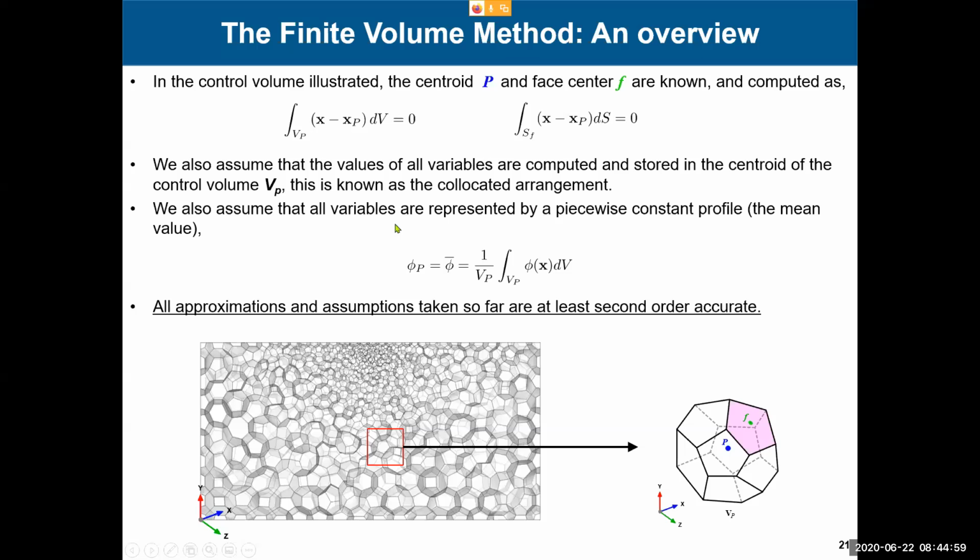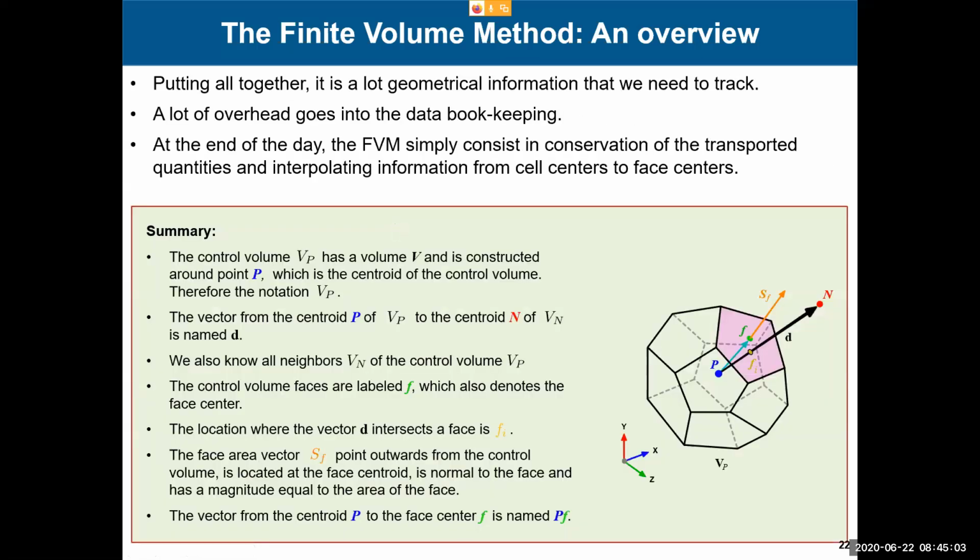So, a few things related to mesh quality. The input and everything together is a lot of bookkeeping, okay? A lot of information kept by the solver in memory to do the computation. Now we're going to see how to use this information. We know the face areas, where the vector connecting two cells intersects this face, so we can know this deviation.